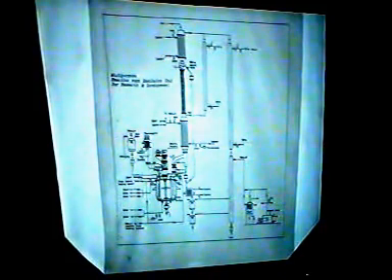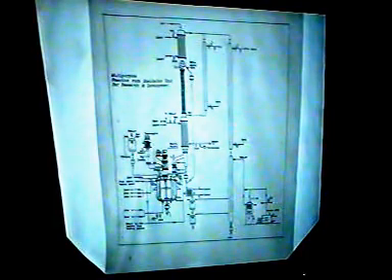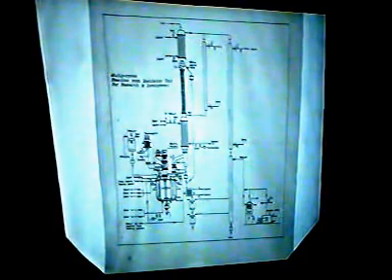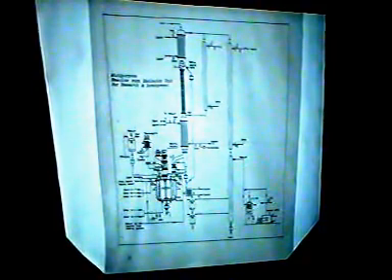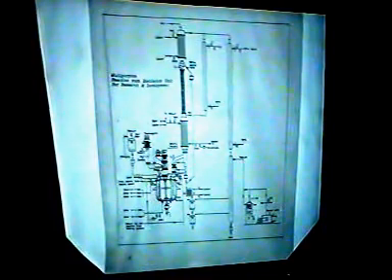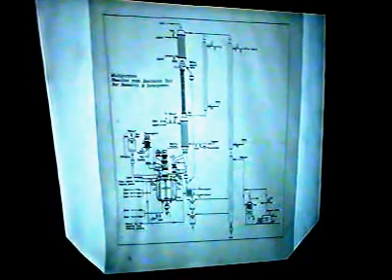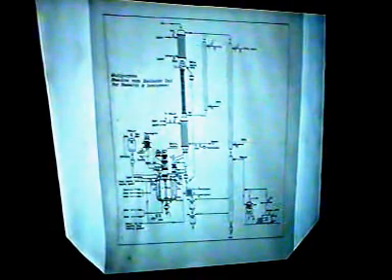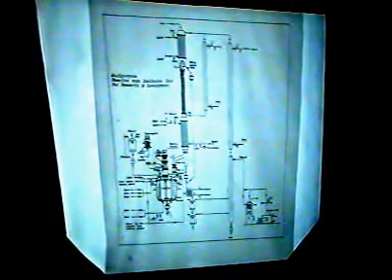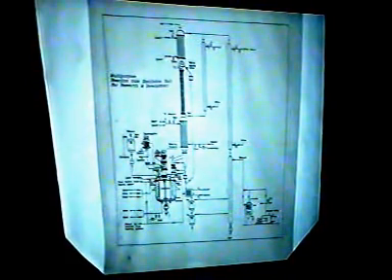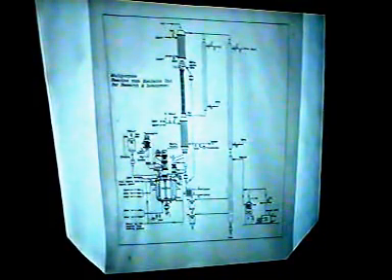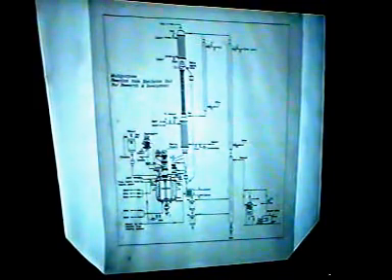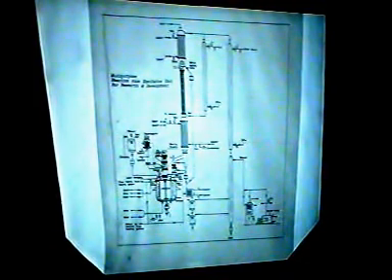Now there is a valve here which can be noticed, which is provided to isolate the rest of this total assembly from the main reactor. This is being done because sometimes if one wants to conduct hydrogenations or oxidations in this reaction assembly, then the hydrogen will also go up and occupy the entire balance of the accessories here, and that's quite dangerous. So we would like to confine the hydrogen gas to only the reaction vessel, and it should not be allowed to go up into the column section there. That is how we have provided an isolating valve there.